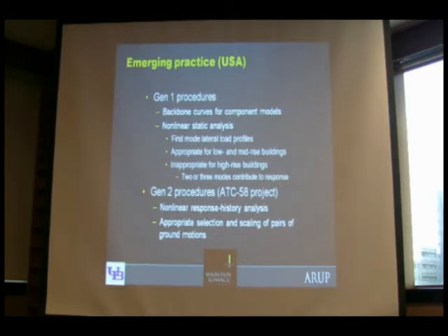But we were moving from a profession that was comfortable with equivalent static analysis. We wanted to get them to nonlinear dynamic analysis, and nonlinear static analysis was the stepping stone. So the Generation 1 procedures are crafted around nonlinear static analysis, but with mention of nonlinear dynamic analysis.